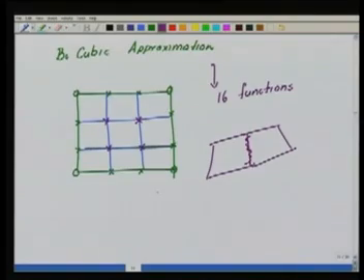Okay, so both these functions on this edge from either side are going to match, because they have to become equivalent to the same 1D shape functions. So because the functions match, the approximation is going to match. Okay, so as far as continuity is concerned, that's not a problem here in this definition.